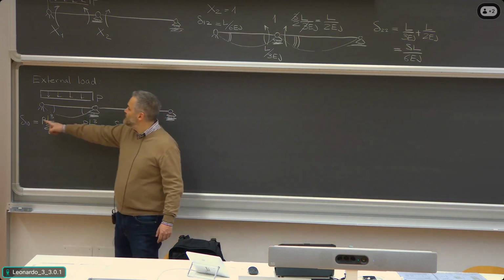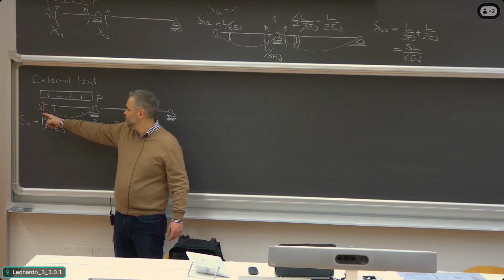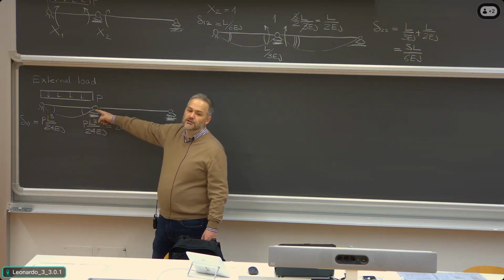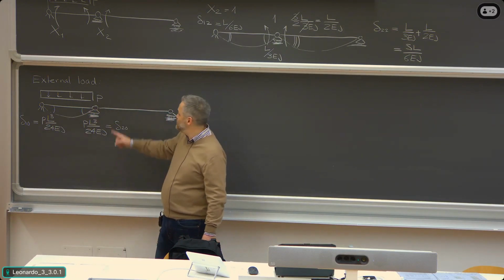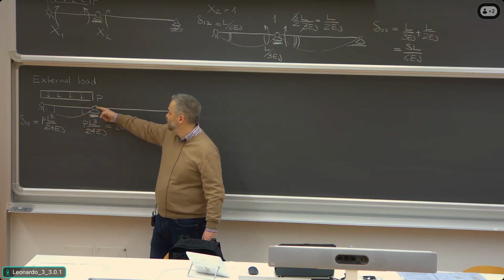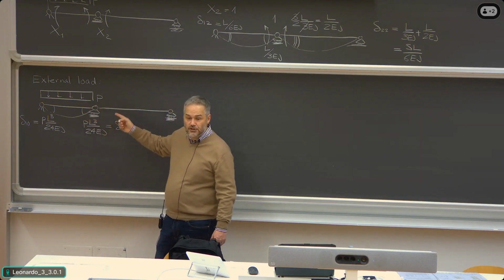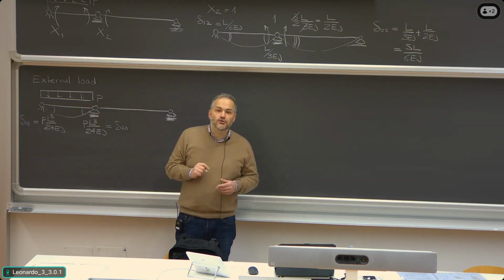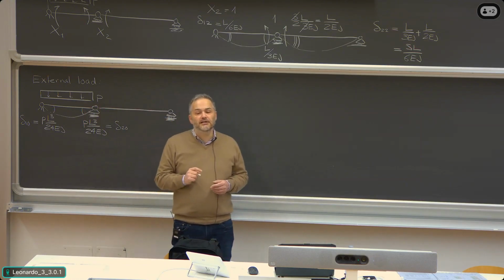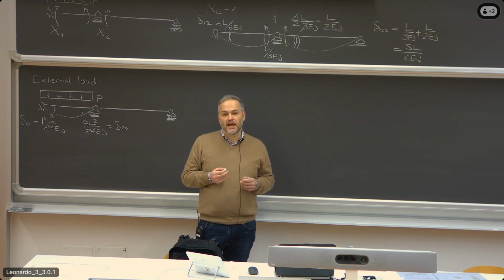We change the fixed end to a hinge, allowing rotations to take place. We change the internal support with continuity to an internal support without continuity. You see it very well here. There is a relative rotation between this span and this span, which cannot take place in reality because the beam is continuous. So the two compliance equations we are going to write will reinstate the compatibility. Okay?